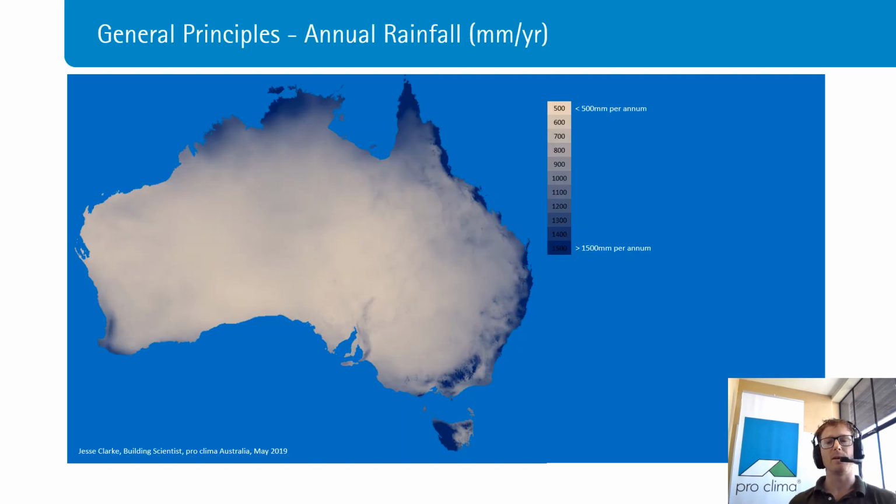So what we're fundamentally trying to do when we design weatherproofing systems and utilize weather resistive barriers is to manage the external rain loads on facade systems or on the whole building envelope. And in particular for facade systems, how much it rains in any given location will determine how we need to design those, or how effective those weather resistive barrier systems need to be.